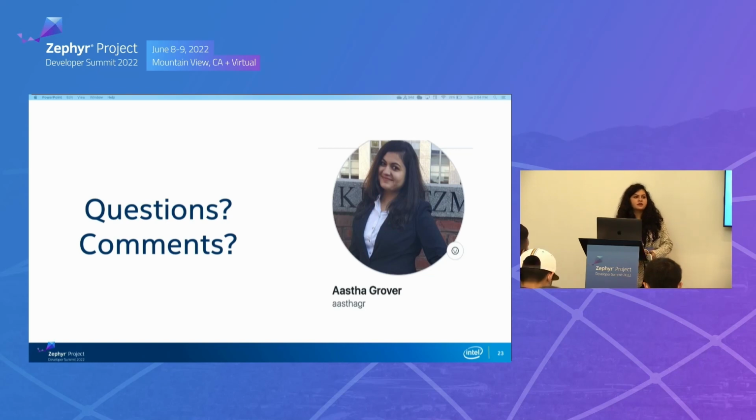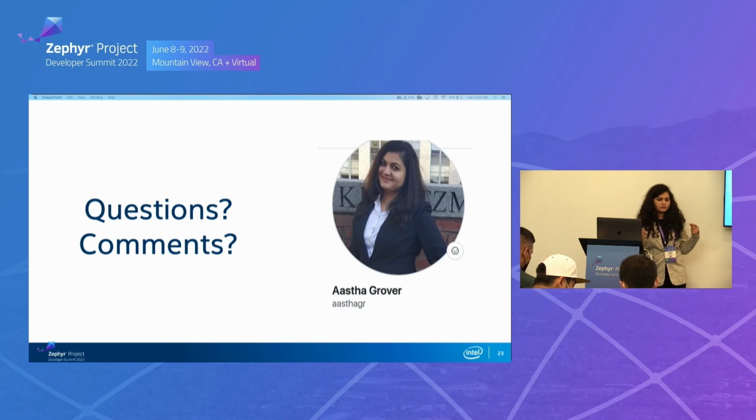Your question is that when we use device testing, the hardware testing gets enabled, but how does the communication between Zephyr and the board work, right? So when you turn on the device testing, Twister identifies the boards which it is connected to and identifies the various details, right? And the serial device is the one where you can notice what the output is coming from the board. Is your question something else, or did I answer it incompletely?